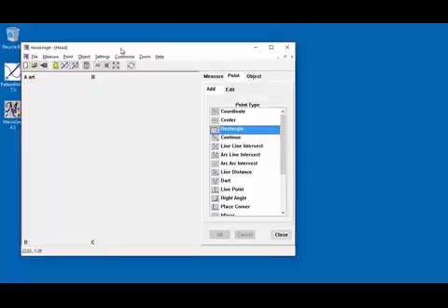Next, let's add point E, which is a midpoint. We're going to say that point E marks a point halfway down the rectangle. We're going to click Point, and then Add, and then Center.